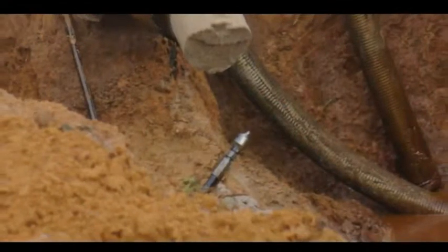So you've got to pig your line even if you do not have rubbish in the line, because pipelines start from one point to another, and along the line, there are a lot of mechanical activities that go on. The road construction works, the ships that crisscross the oceans, the railway construction activities. So a lot of mechanical activities happen. And sometimes you cannot but have some level of accident. So a pig continuously entering and coming out of the pipeline will give you information about what is going on. Next slide.